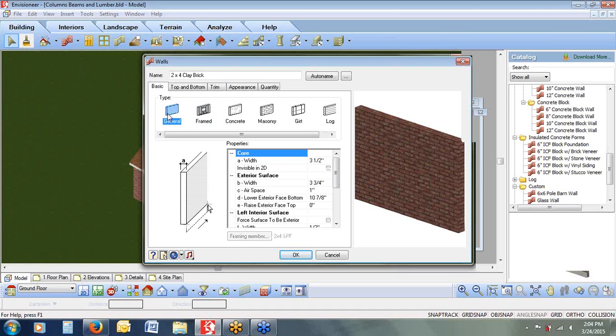For those of you that use our software for remodeling purposes, when you're drawing out and sketching the existing house, you don't want any framing because you don't want to count all of that framing. So set the existing house to general. It'll show the walls. You'll see them in your plan so that you can make your working drawings from them. But because it's set to general, you won't get any framing data from them. If it's set to framed, it's going to fully frame that wall and count every piece of lumber that's in that wall.